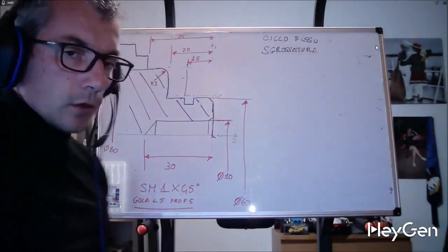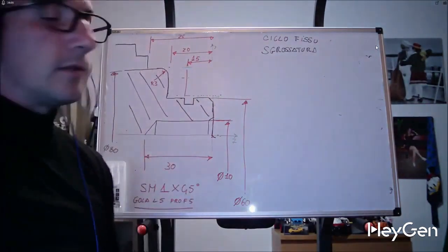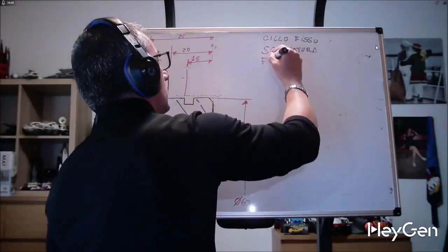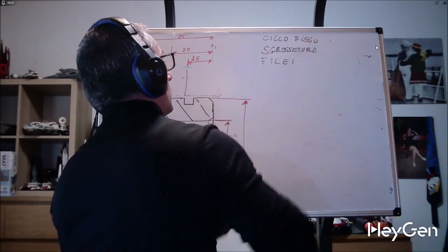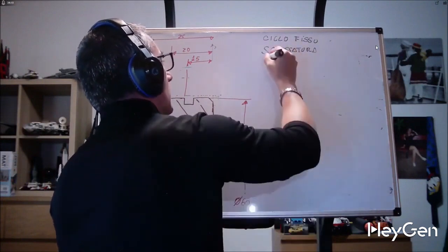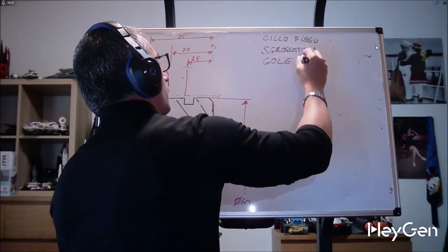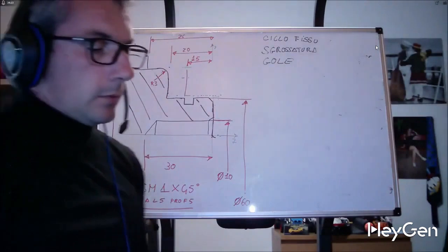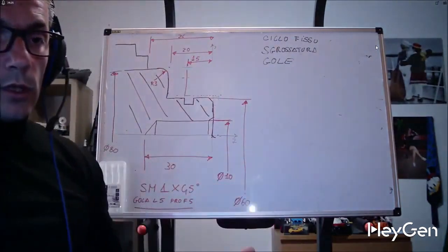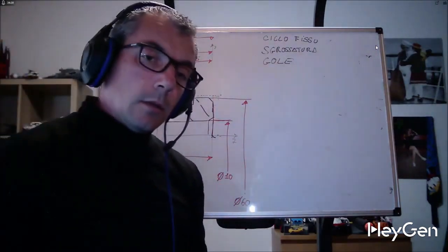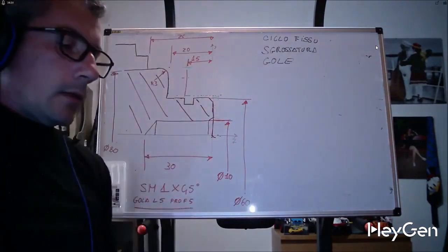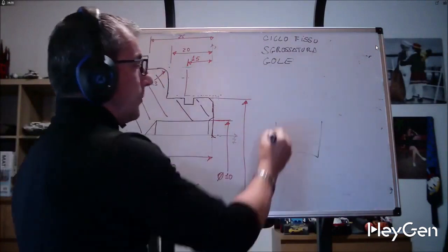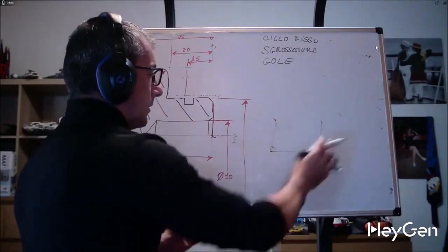The fixed cycle is always a fixed roughing cycle. Some things change, some details, for example, the G that distinguishes it. Then there is the fixed groove cycle, the fixed cycle for front or radial grooves. The fixed cycle for grooves is especially useful when the grooves are large, because you will see, unlike conversational programming, the fixed cycle does it this way, it does not allow you to add chamfers, arches and grooves.